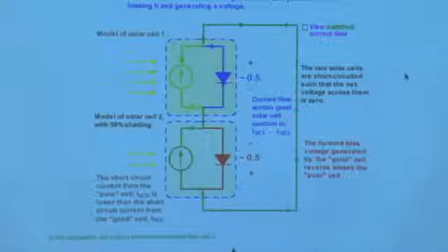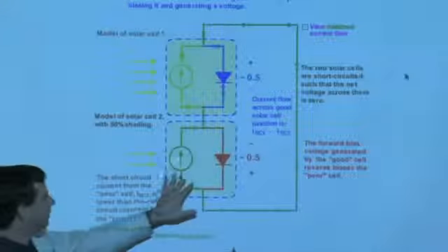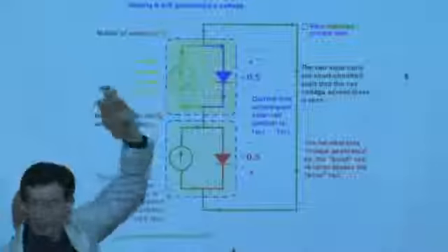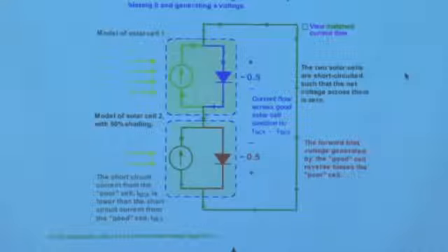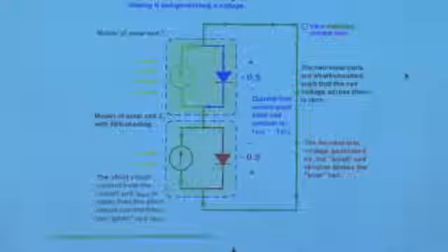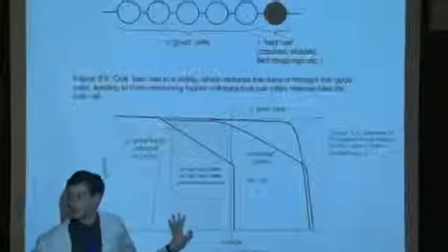Those who are electrical engineers can already begin conjuring up ideas of reverse bias breakdown. But we'll explain why reverse bias is bad in a few. Now, if you had a bunch of these cells connected in series, and they were all producing copious amounts of juice, and you had one bad apple in your string, you could be dumping a considerable amount of power across that one cell. And that's where this graph right here comes from, the power dissipated within the bad cell.